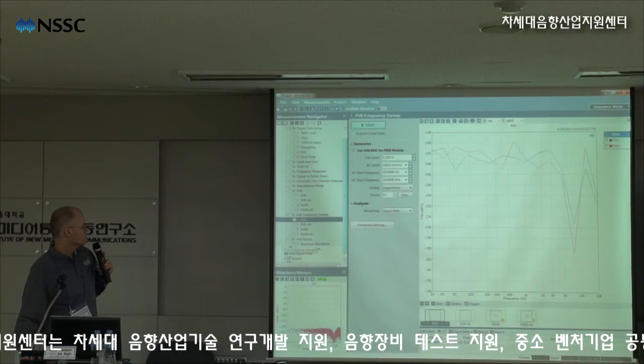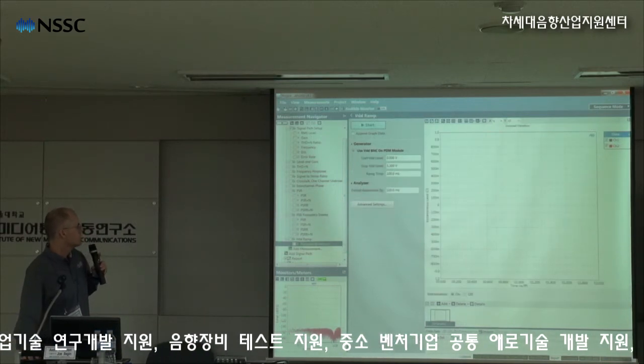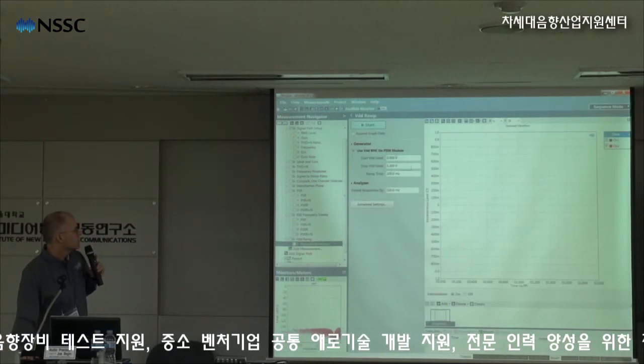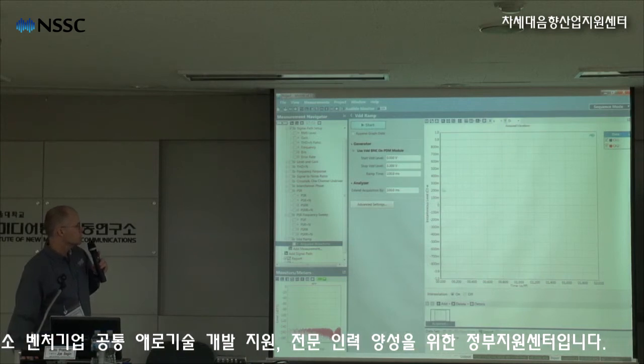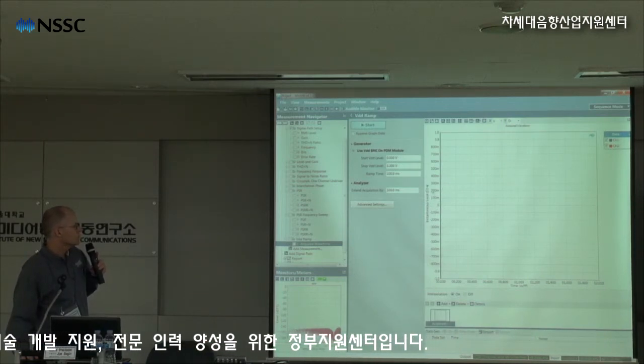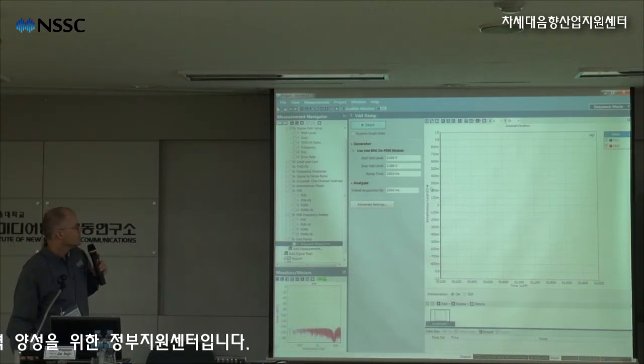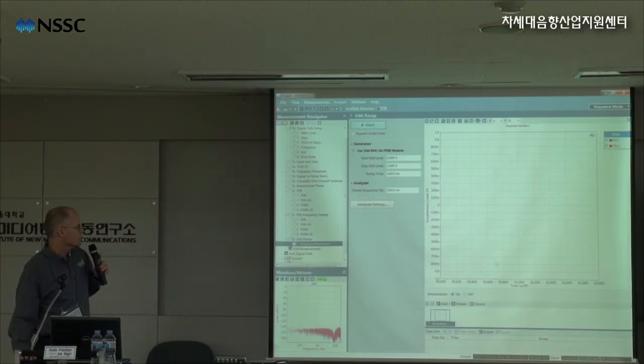And then we have the VDD ramp, and this is showing the instantaneous level on the input versus time. This is going to ramp from 0 to 3.3 volts with 100 millisecond time. Let's just see what that looks like.